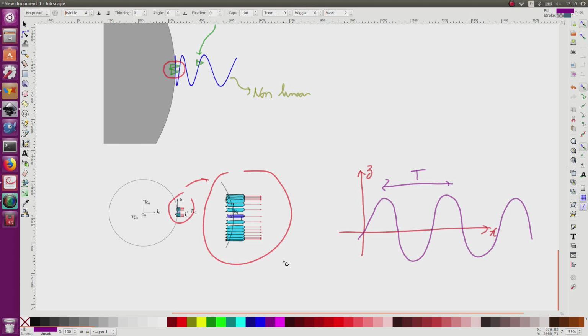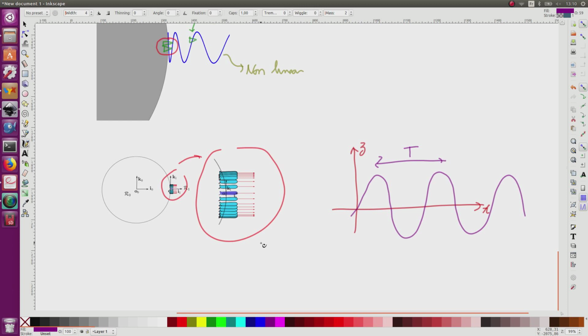So for many applications, I know that I am not moving with this kind of oscillation, such as when I am in an aircraft. I go straight on. I do not have this kind of oscillation. I know these oscillations are dummy, and I can improve the integration method by adding a damping inside the inertial unit in order to damp the Schuler oscillation.